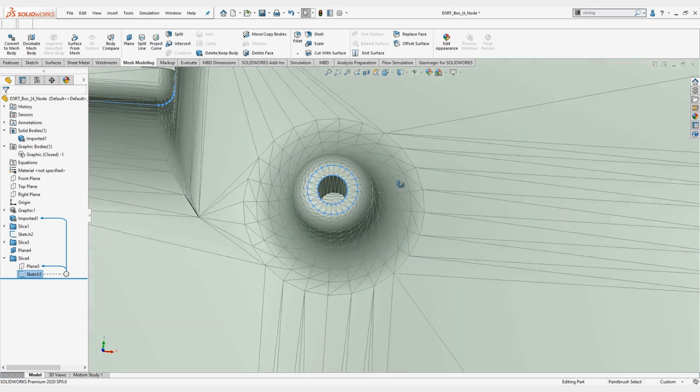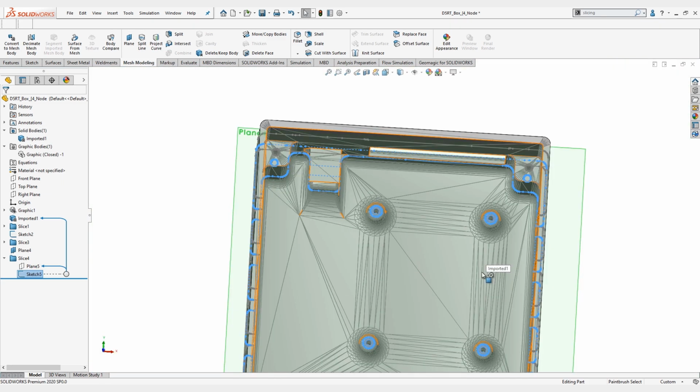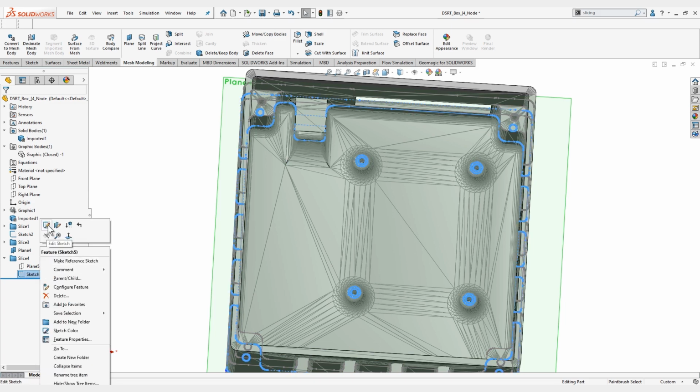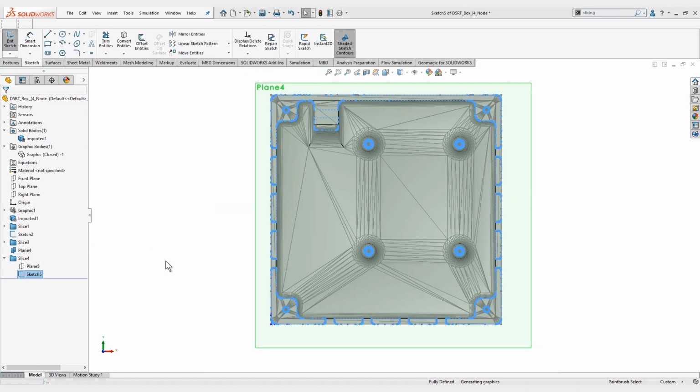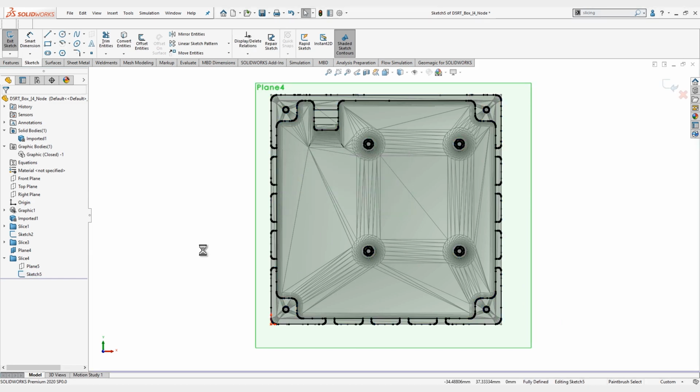So it gives us a nice, in this case, you can see it's given us two concentric circles, showing us the location of where those standoffs need to go. You can see here you are getting some extraneous information in these planes. So it does have all the different hole cutouts and everything over here. But of course, we're just using these as a guide, as a reference. So that then allows us to go in and place that hole and that boss exactly where it needs to be.